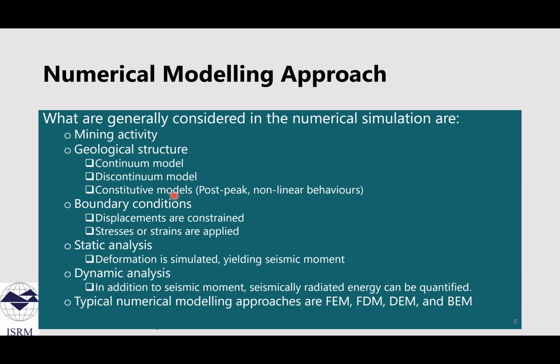However, the comparison of the source state with the Mohr-Coulomb failure criterion indicated that this source state is far below the critical value, as can be seen from this figure. So this means there is also no risk of seismic event at this source location.